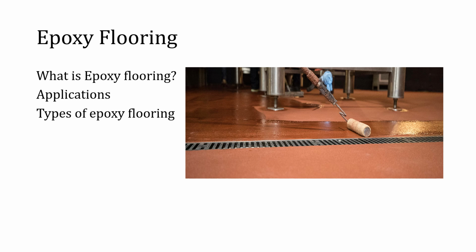Once the resin layers completely cure, the floor system forms a strong and permanent bond, acting as an impervious and decorative barrier to protect the substrate. Epoxy is probably the most widely known resin floor technology as a result of its good mechanical and chemical resistant properties. Epoxy floors also can be customized into a wide range of colors, styles, effects, and decorative options.